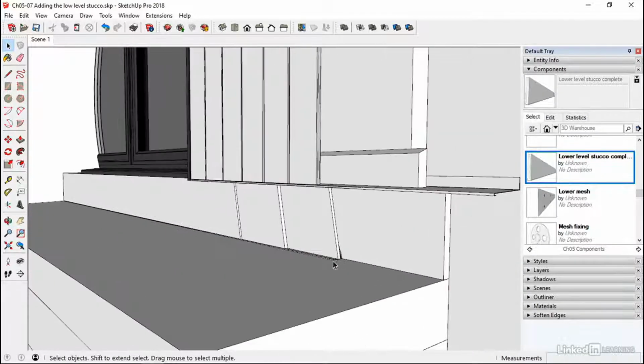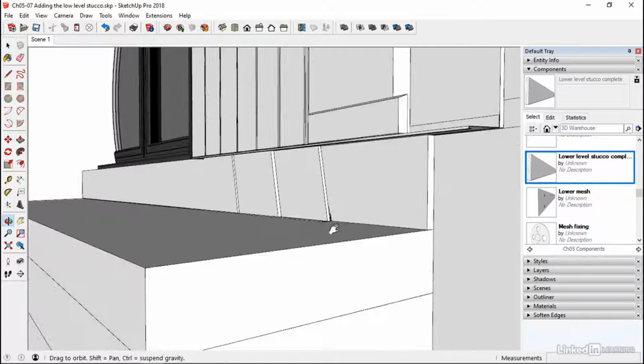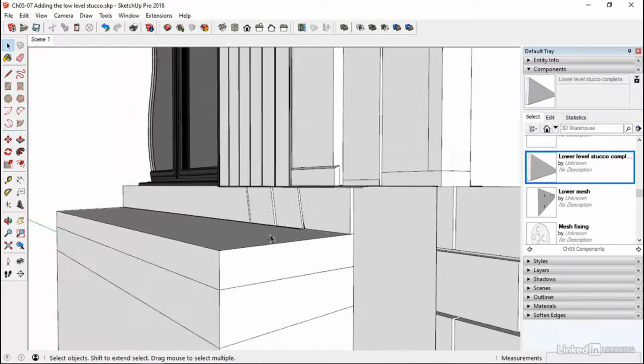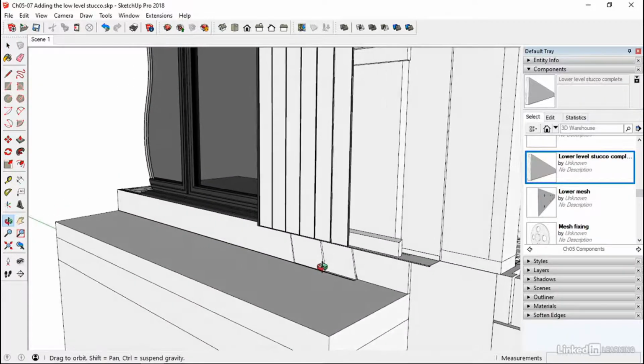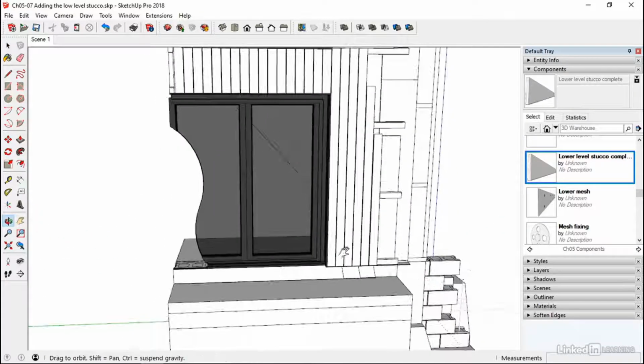So we've got this little bit of beading running there, so we can run our stucco to it. So that's separated from this slightly. Probably, again, a little bit of insulation. We might have to consider drainage systems in the patio. Certainly it's running to falls. Again, this sort of thing will be ironed out on site, but every situation will be different.